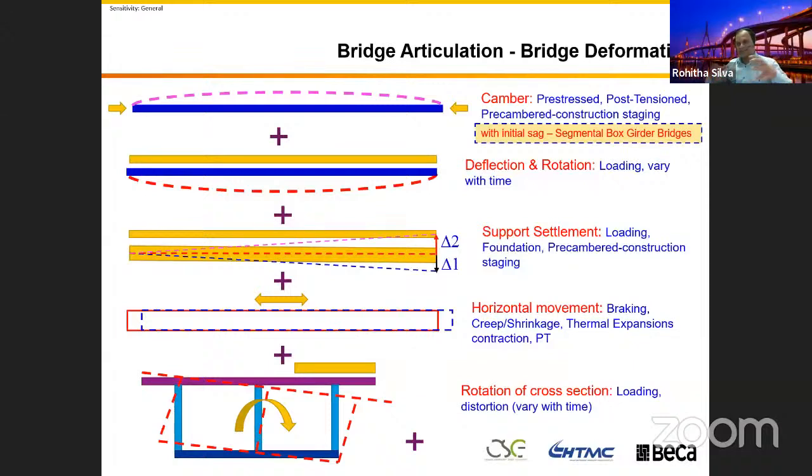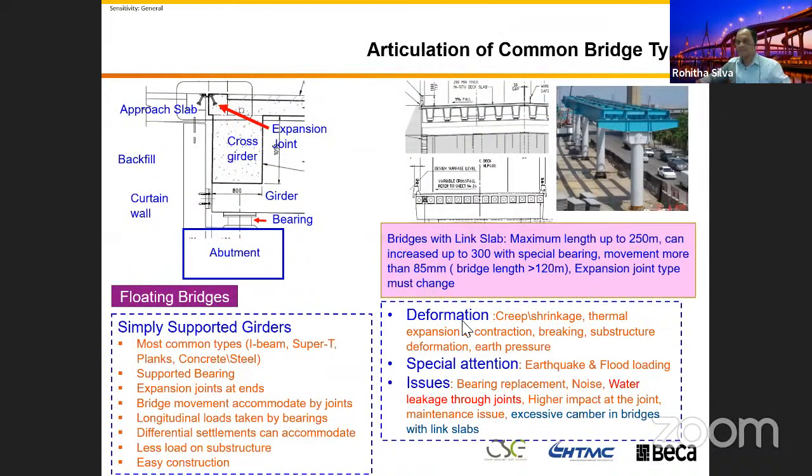I think I explained it to you. There are pot bearings: one is sliding free, it allows the rotation. Another one is the guided one. It guides you like you're driving your car in one direction. Another one is fixed. It is not allowed to move, but it's allowed to rotate. So if you can't work with the pot bearing, then you can go to the spherical bearing. I gave you one classic example, the spherical bearing, the Industrial Ring Road project, and that 1,800 ton gantry we operated. So these are the examples I gave you.